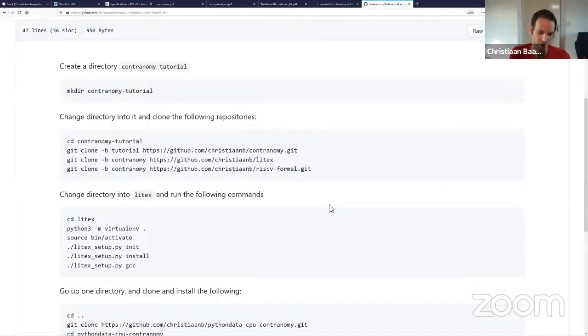And from this Verilog or VHDL code, we can create actual ICs, usually called ASICs, application-specific integrated circuits, using tools that are out there. They convert this Verilog to basically a very fancy SVG, which the wafer steppers understand and can turn into an actual IC.